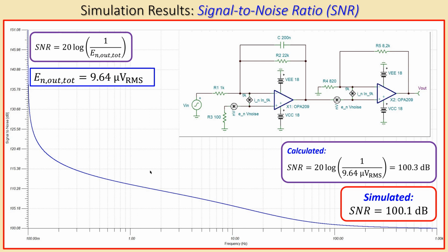If you want to increase your SNR, you need to have less noise than your signal. Then you can consider which part of the circuit is contributing significantly to the noise at the output, and that can be reduced. For example, you can have the ratio here still as 10, so you still have a signal gain of 11, by decreasing the value of these resistors.